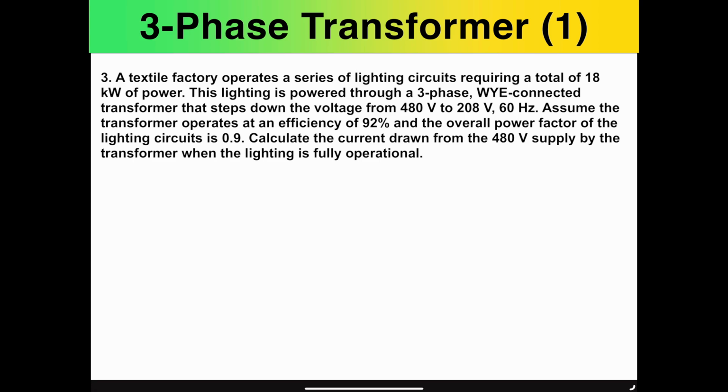So this goes back to how the power is going to be stepped down in terms of the efficiency as well as the power factor that we have over here. Essentially, we typically know that P is S times cos theta. However, that is not the most complete equation because it doesn't consider the efficiency. It only considers the power factor. So we need to multiply that by another factor, eta, that allows us to find the power in the real format. So essentially, this is the efficiency, here is the power factor, and here's the apparent power.